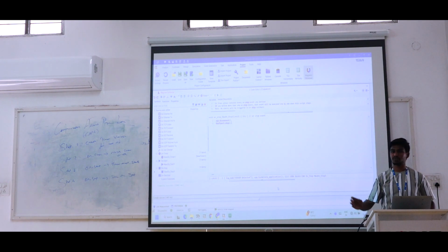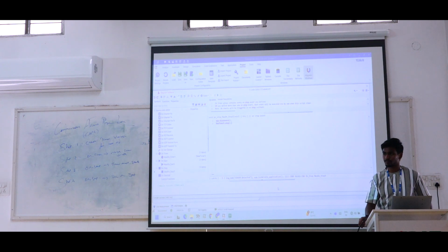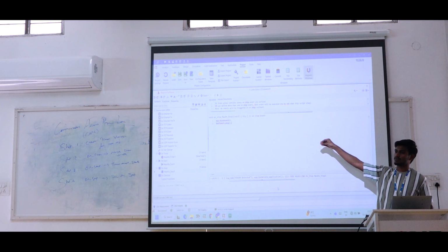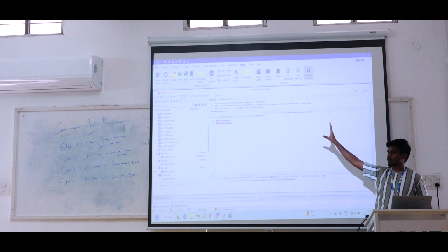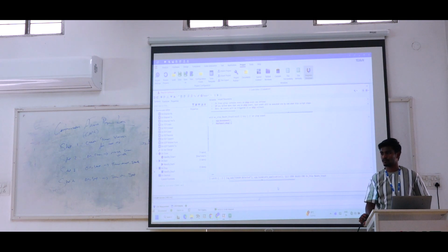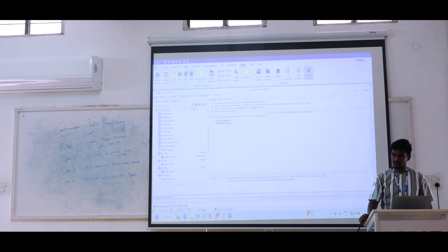Otherwise, because all the values are flash values, if you turned on the RBS but did not turn it off, and you turn off the simulation, the nodes and the messages will not turn off. So whenever you connect, automatically the last flash values will be picked up. Okay, so now we write the program for the new timer.